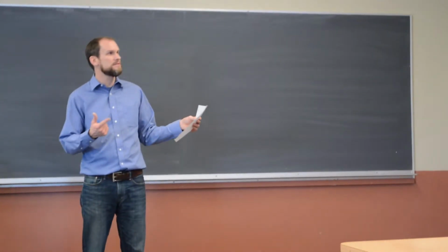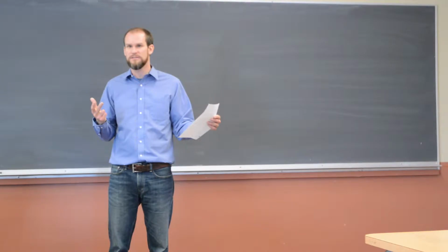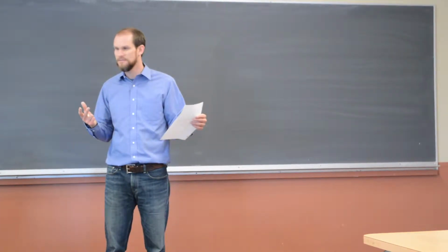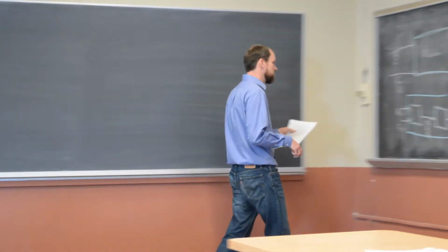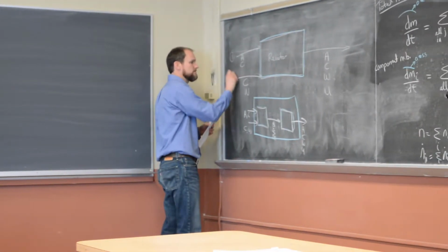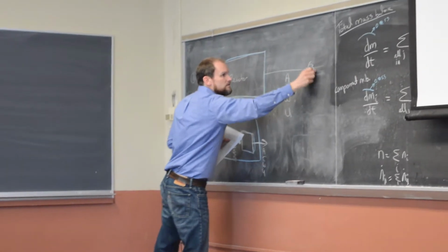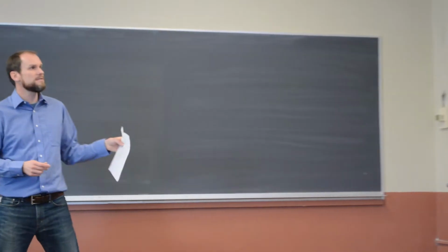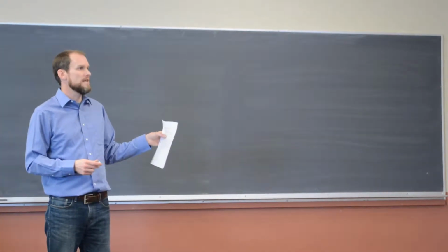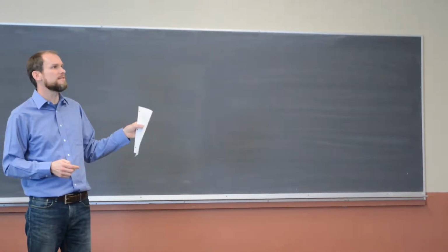Components, atoms, composites, or compounds? Compounds. Define stream variables, number streams, stream 1, stream 2, stream 3. Convert all numerical information into consistent units. Do we have consistent units? Gram moles, great.